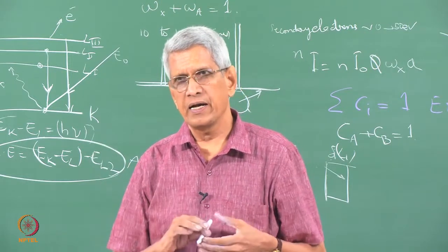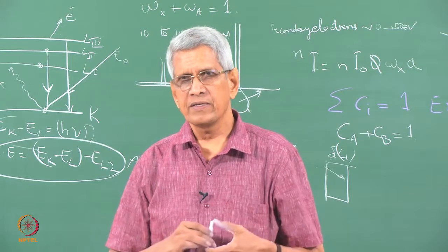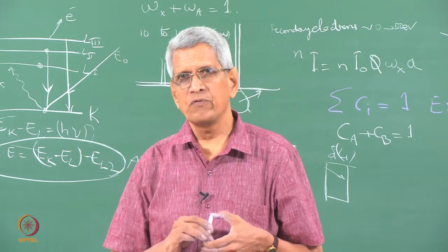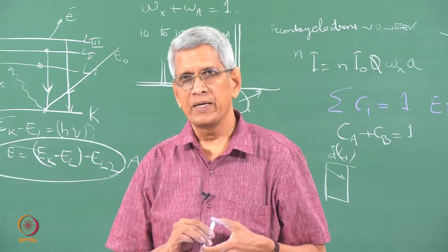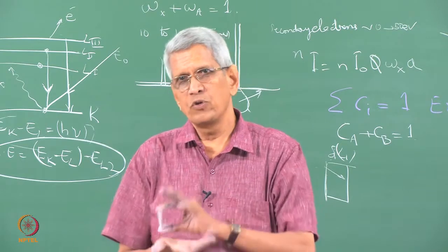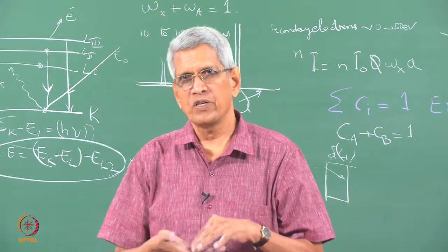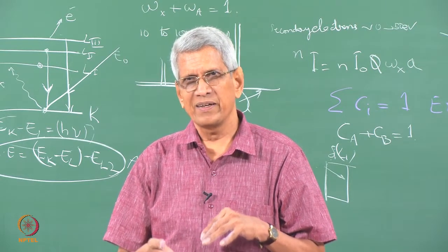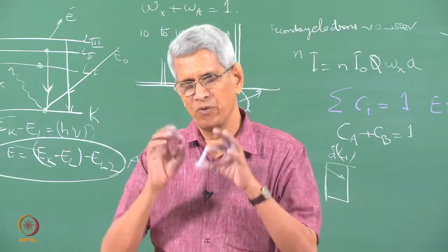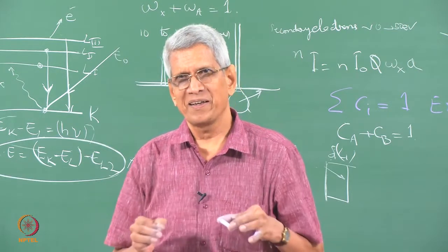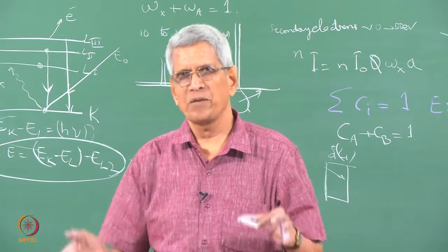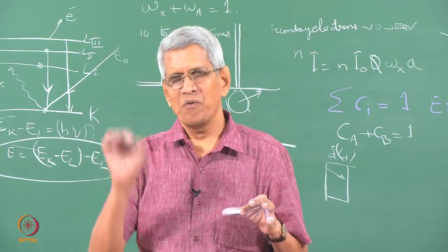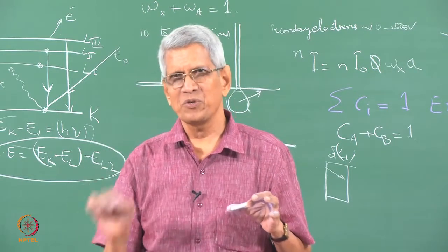So, essentially in SEM, the interaction volume is about 1 or 2 microns. That means that we do not get the true surface composition of that sample. And another thing is that since we do not know the thickness of the second phase particle, there is always a doubt whether the entire signal is generated from the full volume of the precipitate or not. Whereas in the case of a TEM, this doubt can be cleared because we are able to observe the image of the precipitate. We know how much the thickness of the precipitate contributes.